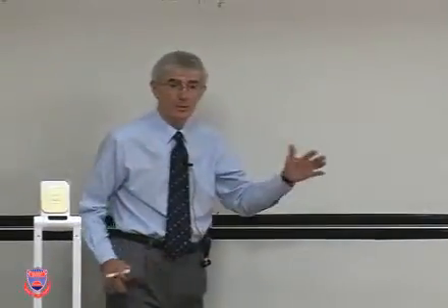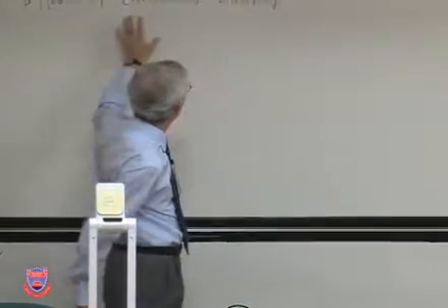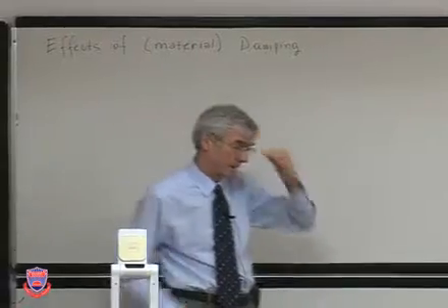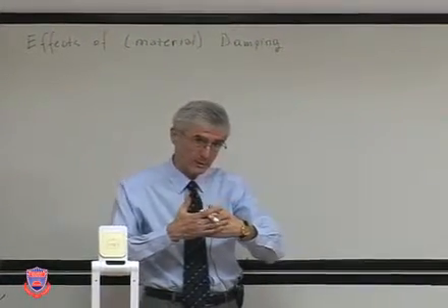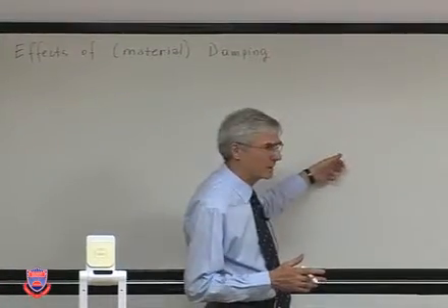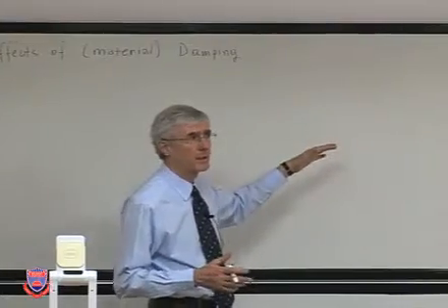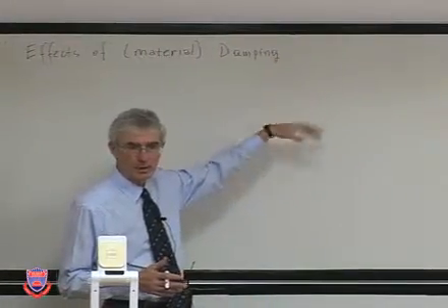And there are a number of different ways of doing this, or a number of different damping mechanisms that exist. Joints, for example, when two surfaces touch one another, or using polymeric materials. If this is like a thin plate and it's vibrating, you can put a polymeric damping material and so on.